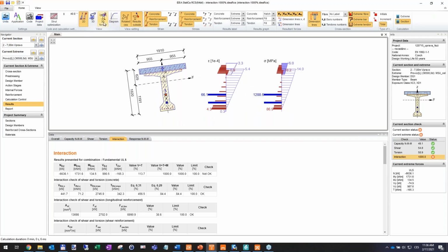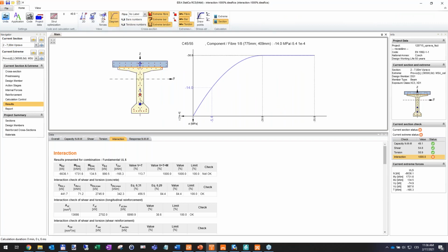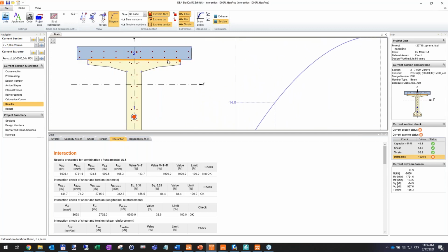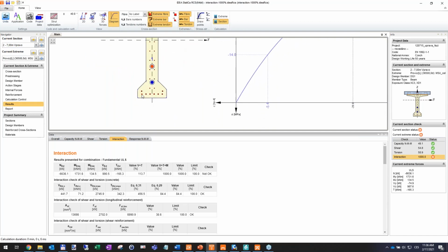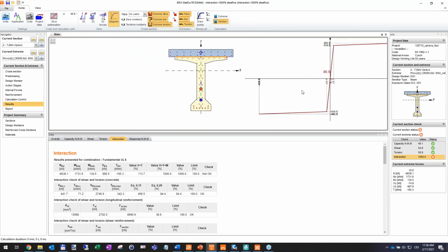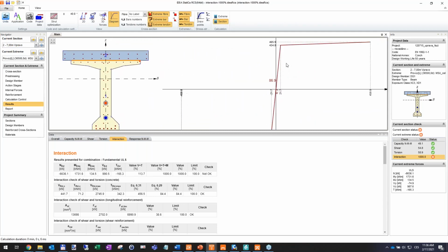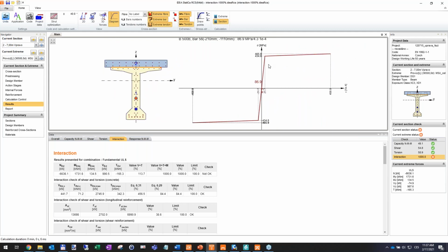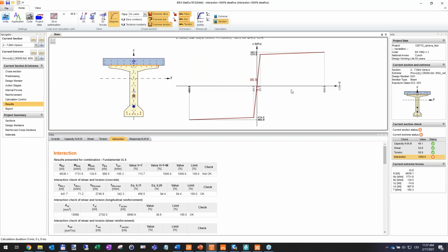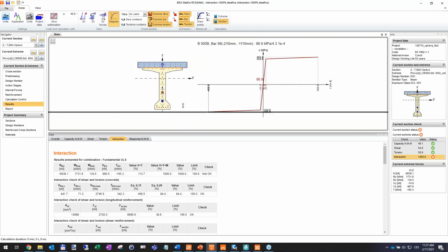Again, we can switch between the type of display. So if we click on a diagram and, for example, look for the most tangent rebar, we can see where we are in the position, if we are on the plastic branch, or in this case inclined branch, how far we are from the limits, for example.